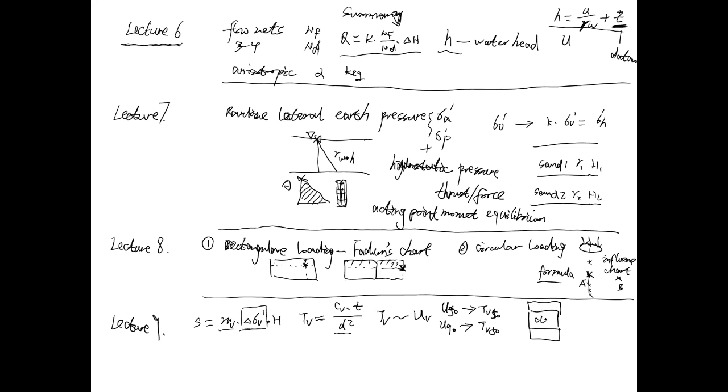If you see, the middle will always be the clay layer, so when talking about drainage, it's clay or silt. If below there's rock, or clay, I mean the dead rock, there's no gap, no water can penetrate, which means it will be an impermeable layer. On top you will have sand or gravel, which is a permeable layer. So that's one-way drainage.